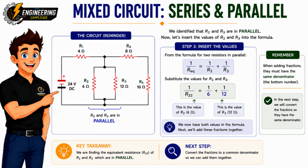Now that we've identified R2 and R3 as being in parallel, the next step is to combine them into a single equivalent resistor. Whenever 2 resistors are connected across the same 2 points, we use the parallel resistance formula. The formula is 1 over the equivalent resistance equals 1 over the first resistor plus 1 over the second resistor. Or mathematically, 1 divided by R equivalent equals 1 divided by R2 plus 1 divided by R3.